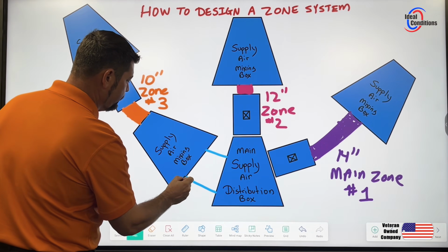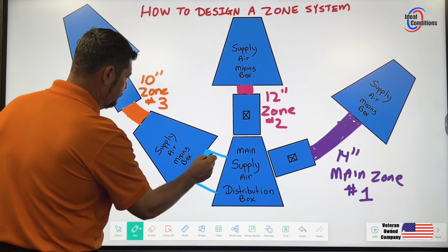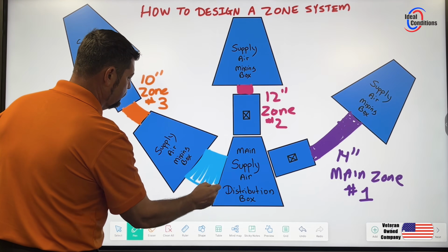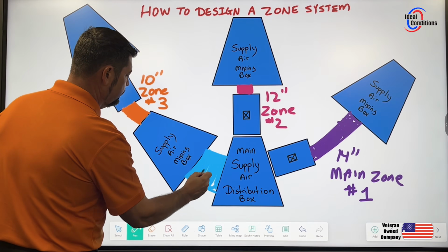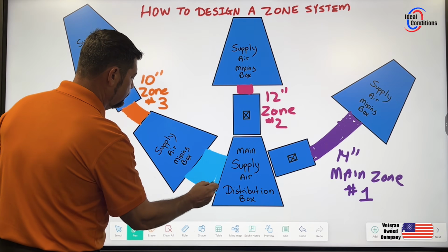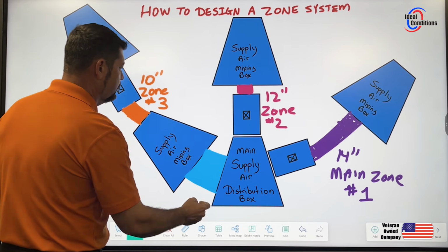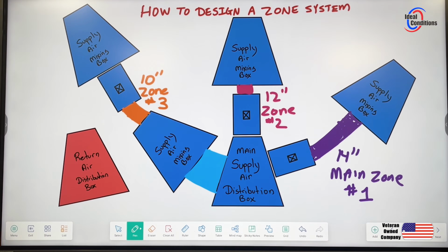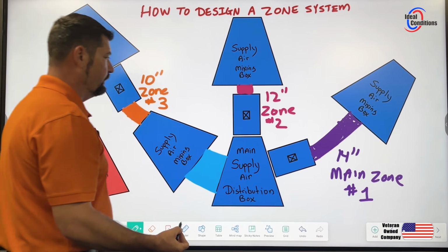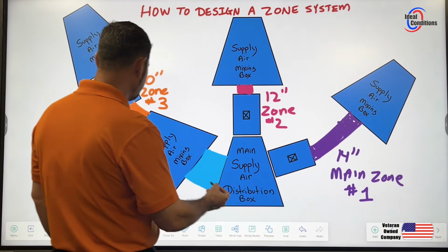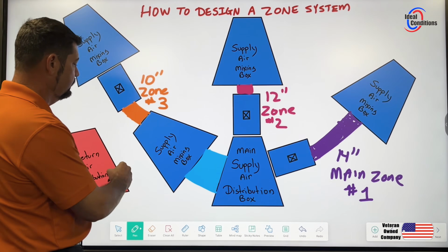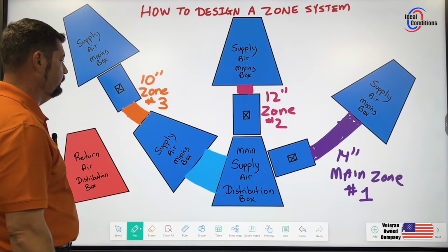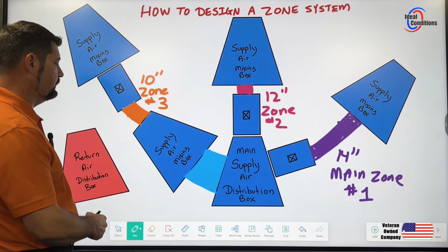This is no damper. This is just a trunk line. And this trunk line is there to carry the sum of what is going to be absent to allow that bypass to open up based on static pressure. So basically, if this is going to be a 16 coming to here, then I need to be 16 going to it. So we'll do the math on that to make sure that's accurate.